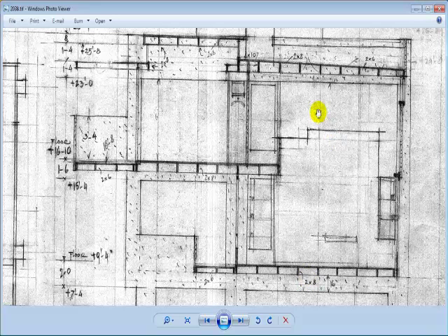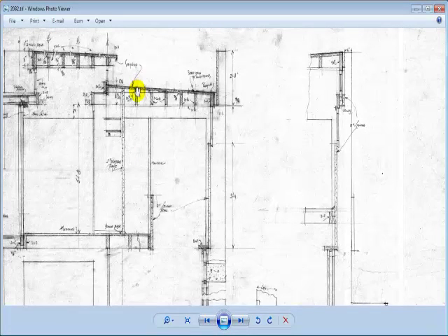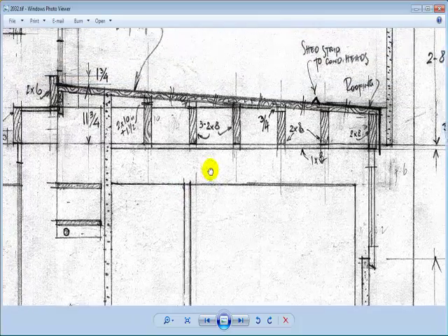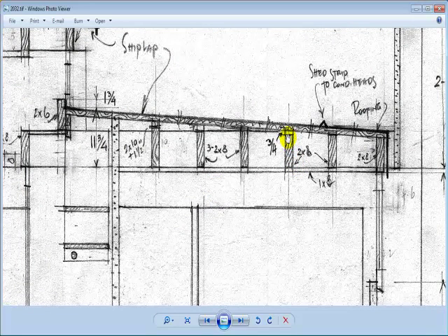But up at the roof level, there's something even a little more interesting going on where we have these 2x6s, then 2x8s. The roof planking is actually sloping. And what ends up happening is he has to go through and fill in the gap, which is going to turn out to be an incredibly painful detail. I don't think this detail got repeated a whole lot, because as we continue to move through all the Schindler buildings, you'll see he doesn't use this system that often. We have the 2x8s, and there's about a 3/4 inch piece in there.